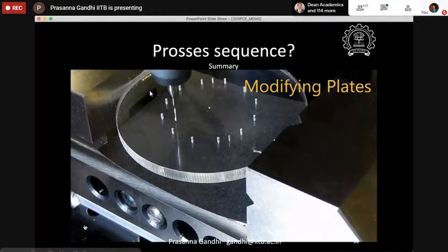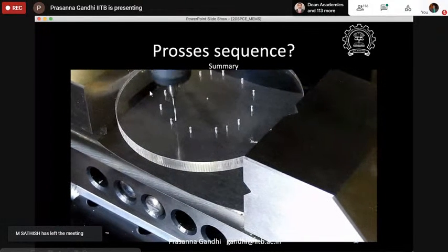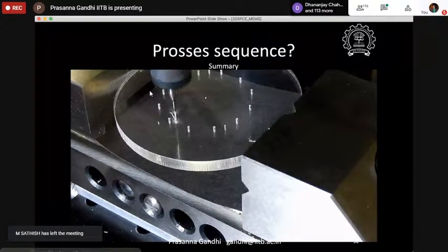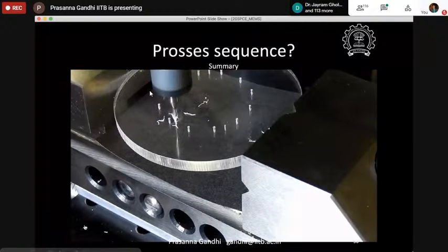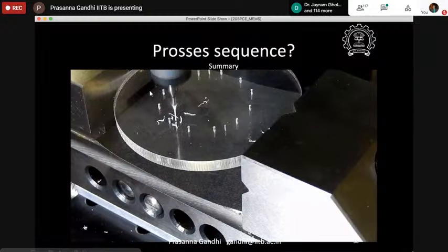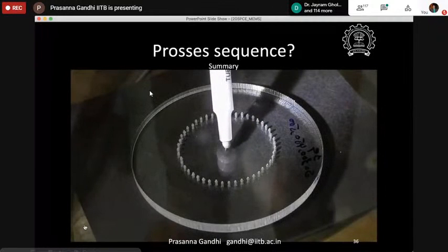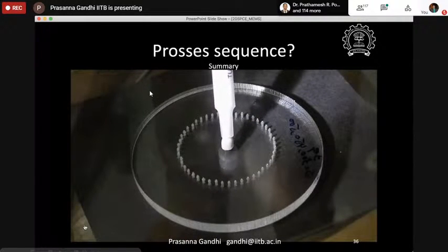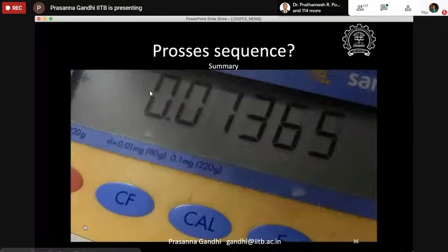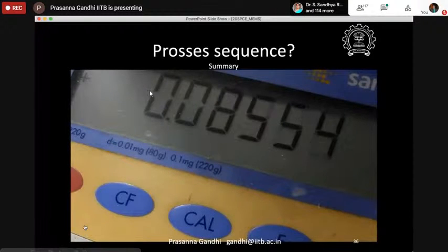Whatever this machine that you see here is some kind of a small homemade micro milling machine, which uses motors meant for aero modeling. These propeller motors are very high speed motors that are used to do this high speed spindle or macro scale drilling. So you do this for a calculated quantity of